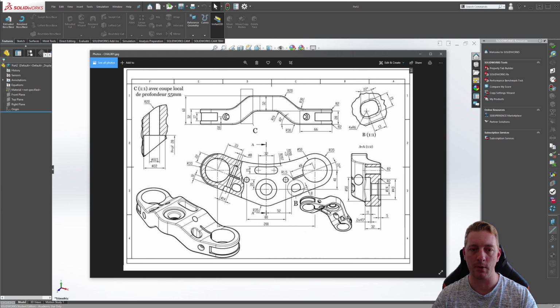Whenever you have shapes like this, where you have one shape from a top profile, but from a front profile you have a different shape, you should use a feature called Intersect. This way you can build two shapes, a top profile and a front profile, and then intersect them so that the mass in the middle between those two shapes is kept. I find that is the best way. So you're creating two solids and then intersecting them to create one solid body in the middle. So that's what we're going to do in this lesson. I think intersecting parts is a really important thing that you should take from this lesson.